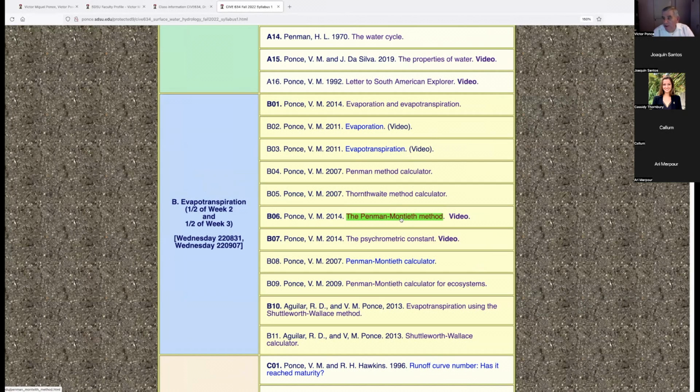Remember, I did mention to you in the past, several times I believe, that there's a hierarchy of models in hydrology. The top models are deterministic. The second level or second tier are the stochastic. So when you give up on the physics, you can always resort to the games of chance, stochastic. The third level is the conceptual, and the fourth level is empirical.